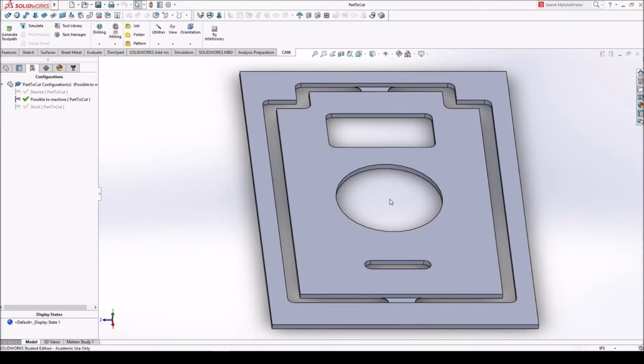Instead, this part will be machined from a somewhat larger plate, allowing for some material to remain, acting as tabs between the large plate and this cutout. This ensures that the plate does not eject from the cutting mill until an operator has manually removed it. In addition, the corners of this square cut, as well as similar corners in the outline cut, will be rounded due to the machine having a certain radius on its tool bit.